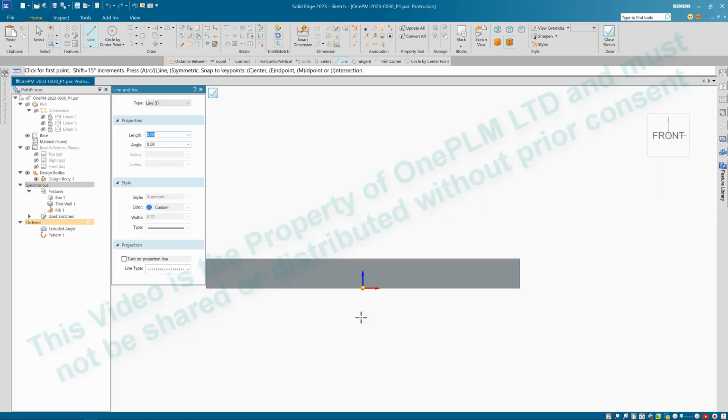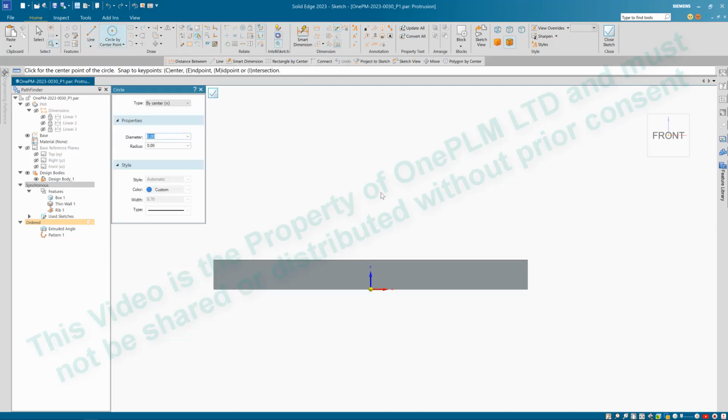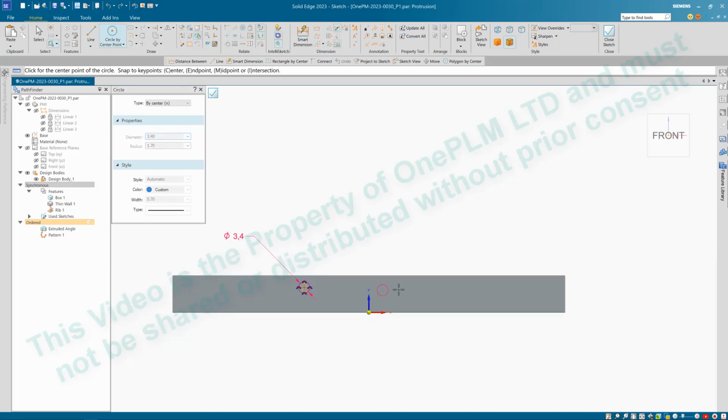And the holes that these go into are about 3.5 mil. So I'm going to do a couple of holes, 3.4, and I want to place these in line along here. You'll notice if you're snapping to geometry and it keeps snapping there, make sure when you select that there aren't any little icons being picked up by your mouse, otherwise you're creating a relationship to the underlying geometry.